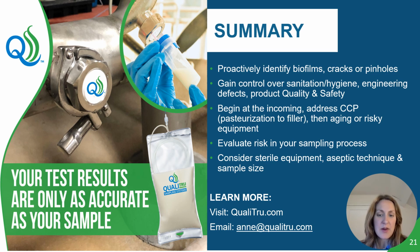If you go through and evaluate the risk in your sampling plan, that allows you to understand what type of equipment you really need. Does it need to be aseptic, or can it just be a sanitary designed sampling valve? What risk does that cleaning process have when it comes to the quality of your sampling? And does that introduce potential contamination into your process or into your sample itself? And then what is the sample size that you need? Do you need a representative sample, or do you need to have a quick grab sample?